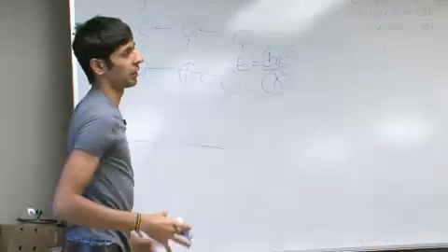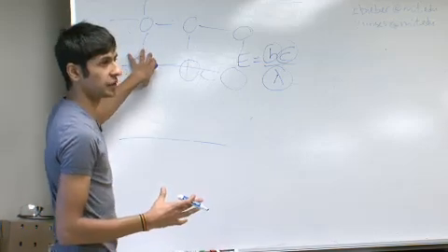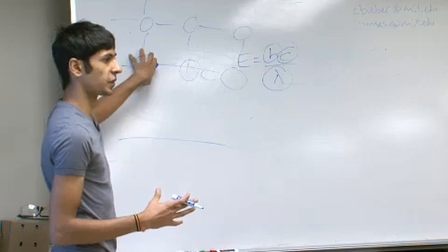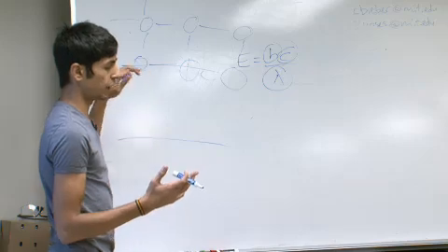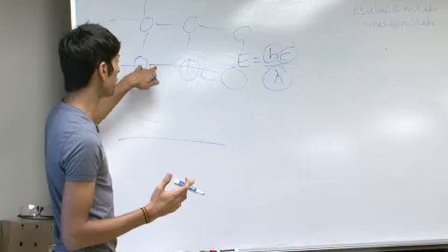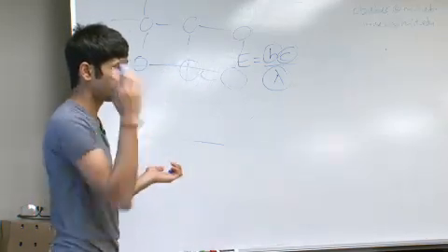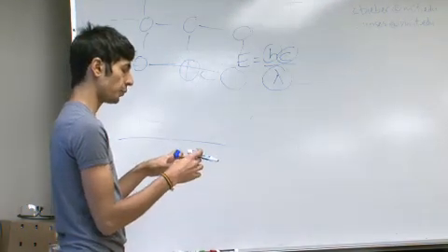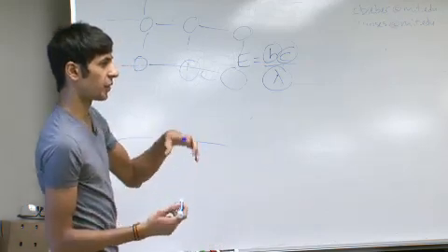And so they're all bound in this lattice. What happens is they don't have free electrons right now, but you can get a free electron from them if you excite the electron with enough energy. If you have a photon coming in with the right amount of energy to excite an electron out of one of these bonds, out of the lattice, the electron becomes excited, and you then get an electron hole pair.